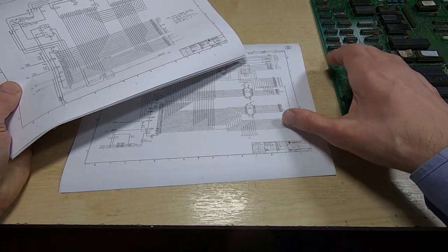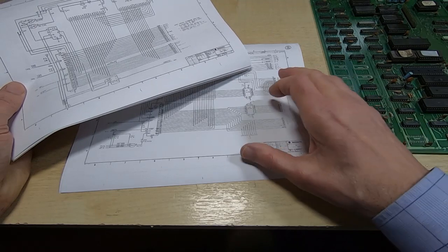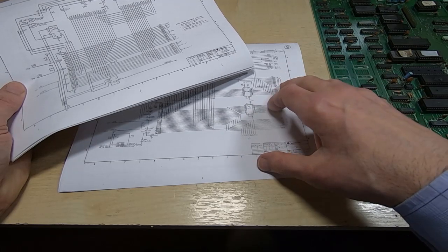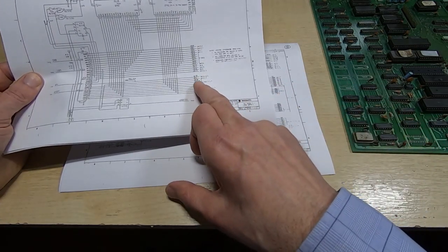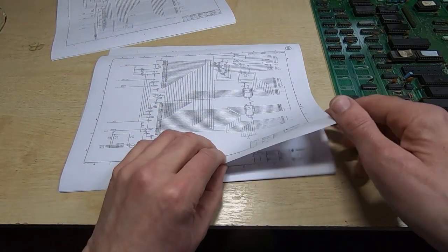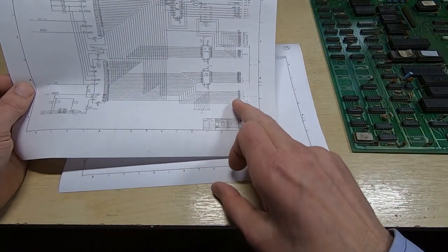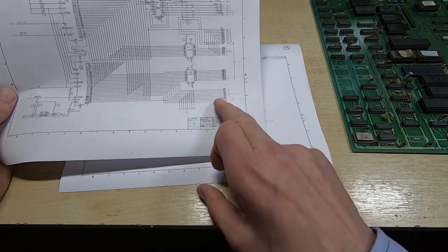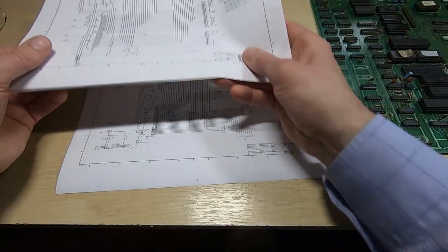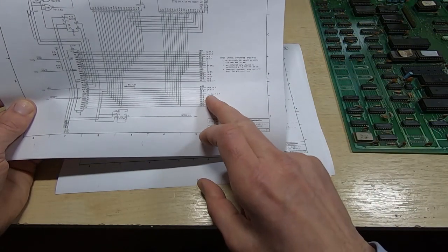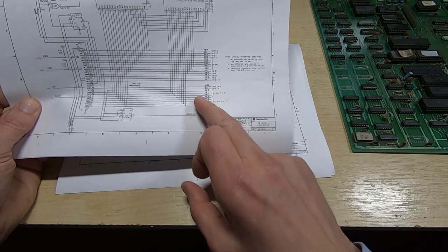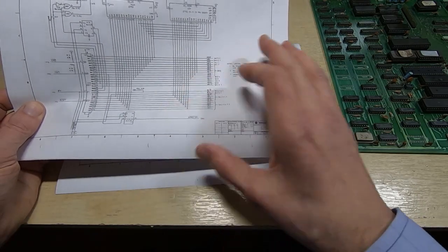And really there's only a couple of areas where we have crossover on these. They don't really share resources, they don't share RAM, anything like that. They don't share address bus, they don't share data bus. However, if we look at data naught, for example, it says sheet 2, 3, 5 and 7. But if we look at, for example, sheet 8, we have a duplication of those names. You won't be able to see this, but the sheet numbers are completely different. Remember I said that sheets 1 through 7 are for the 6502. So because these connections only go to sheets 2, 3, 5 and 7, it means these don't go anywhere near the Z80. And the same is true with a lot of the signals.